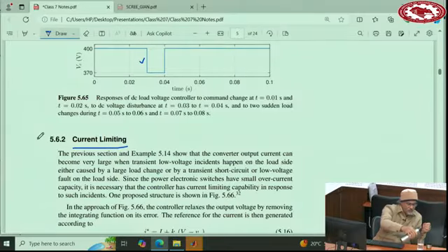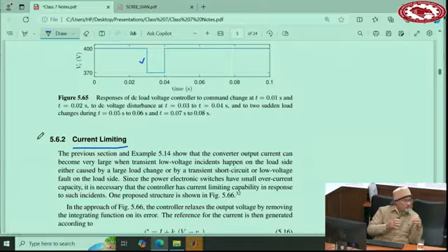That's a very good question. However, my answer is, when you say this converter is supposed to operate at the rated 1 kilowatt, that's the rated value. It can go from 0 to 1 kilowatt, and even maybe slightly above 1 kilowatt, depending on how much room you have given to your switches and everything, because switches really determine the rating, right? So in this kind of application, this is the common practice. You design it for the rated value, because we don't have any other really. If we don't do that, what should we do? We should start from somewhere.